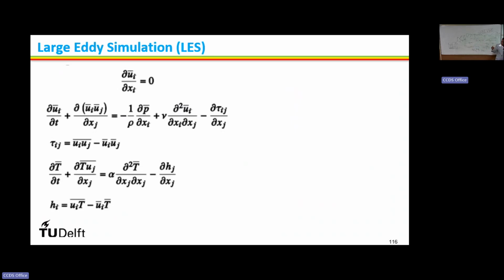At some particular location or point, you need to put a probe or monitor these statistics, right? This needs to be sufficiently converged. It takes a long time to converge, meaning there is still a little bit of change. That's why LES simulations normally span weeks of time. With a small time step, the computation takes sufficient time to get an independent or converged result.